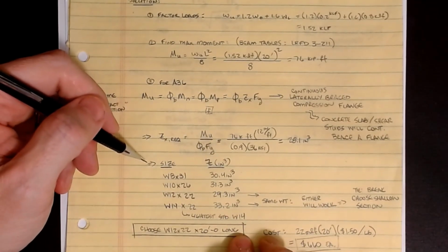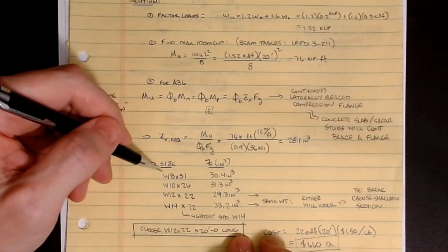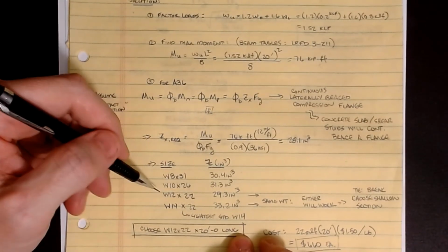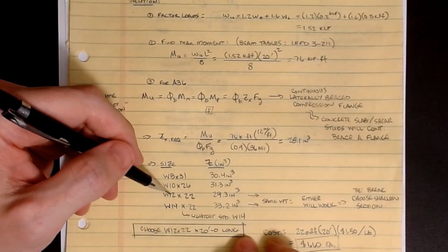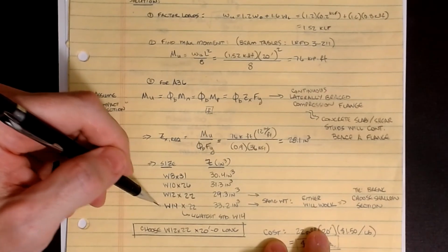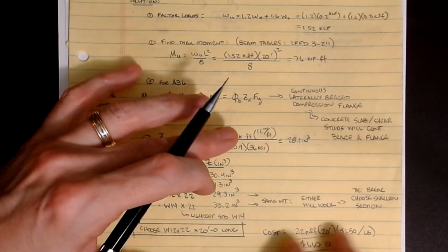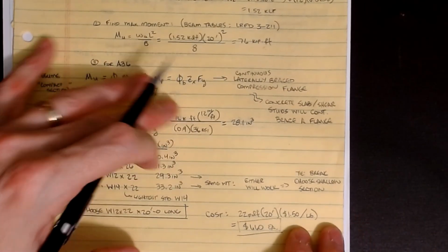And so if we want to choose, okay, then we can go through and we can figure out, well, which one do we want to take? And it's obviously the one that's the lightest weight. Okay, so we're going to take either the 12 by 22 or the 14 by 22. This is actually the lightest standard W14. Okay, it's the same weight, either will work. Okay, so what we can do is, well, how do you break that tie?